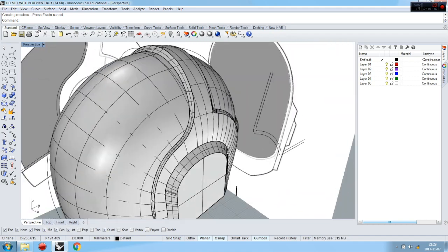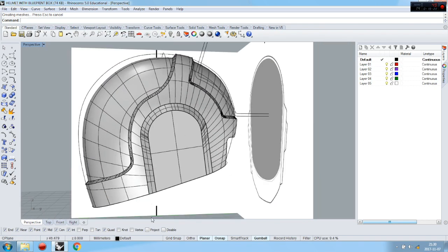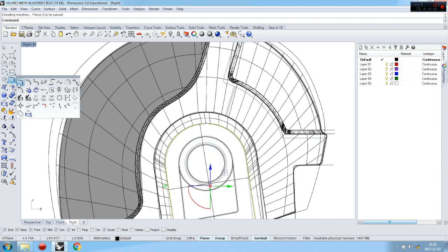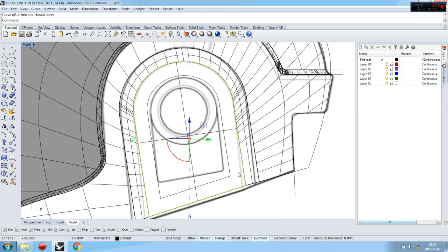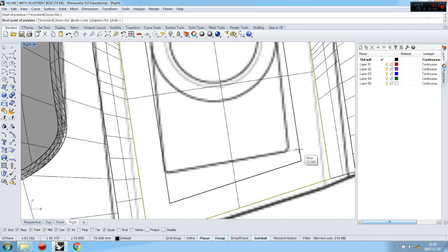So now basically we are already at the end. Now we need to find out what's left. Actually, there's one thing left. I need to get that curve and offset it again. It's going to be like a 2, 4, 3. 3 is great. And yeah, I need to change that bit and trim it like that, and then connect it. We mean join it to be one piece.